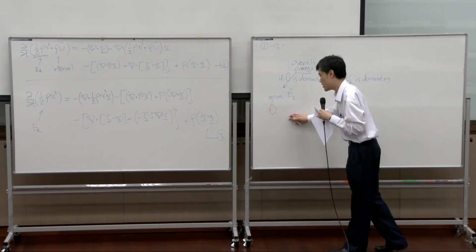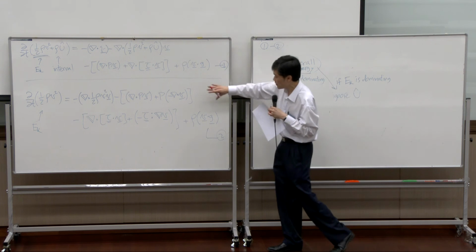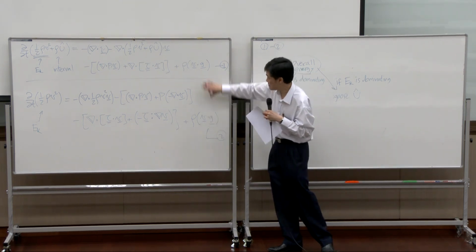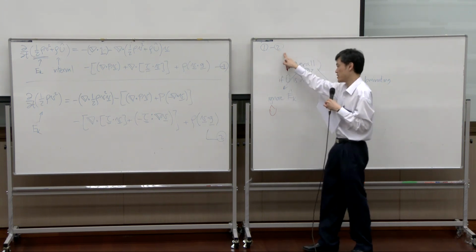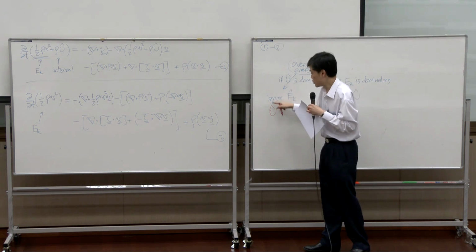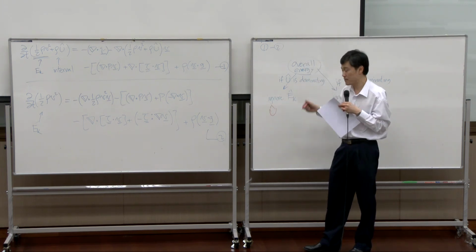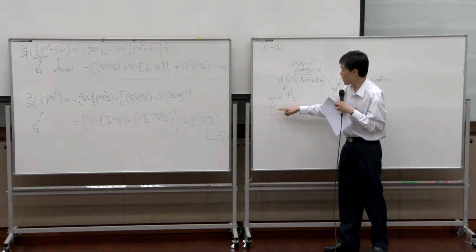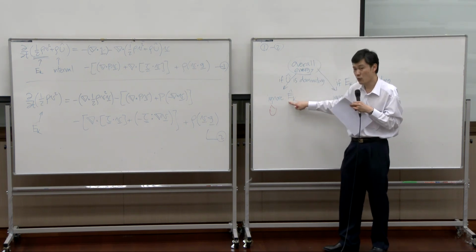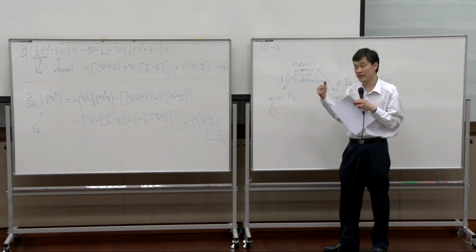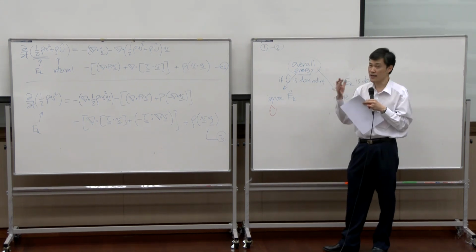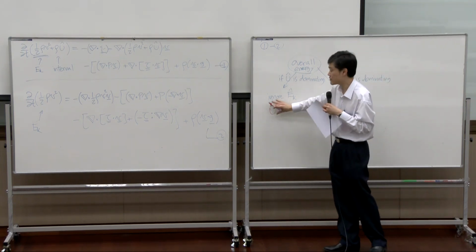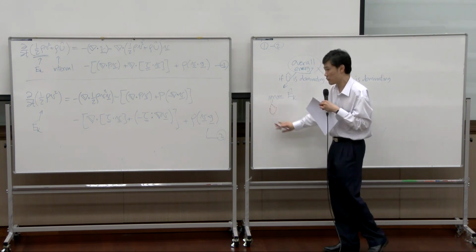Of course, there will be potential energy as well, but let's ignore that because we know potential energy is embedded in gravity. This gravity would cancel out anyway. So the result from equation 1 subtracted by equation 2 would be equation representing change in internal energy of the whole system. This equation will be useful whenever we can ignore kinetic energy. In other words, whenever that your temperature has changed. Okay? And in this session of energy transport, energy or temperature of the system always change. So therefore, it's always dominating. This equation will be very useful later on.